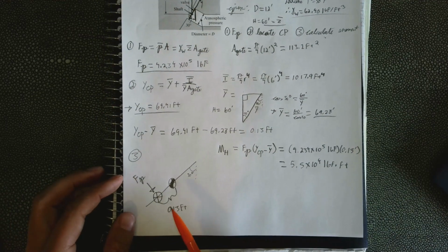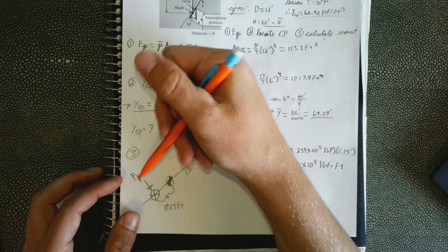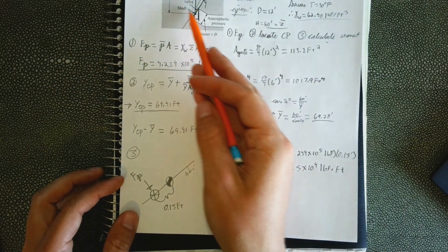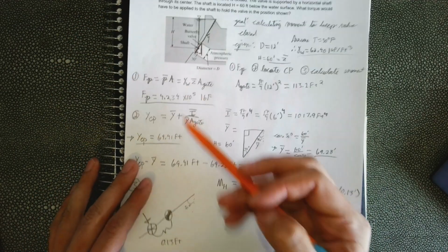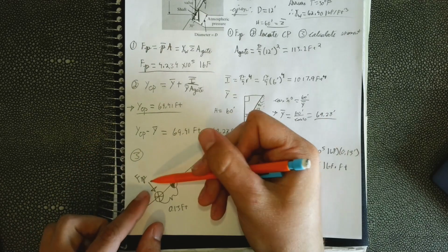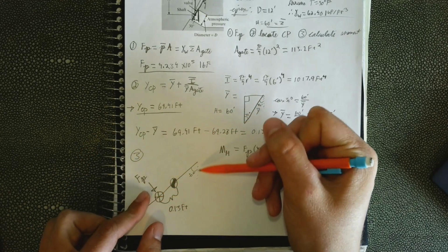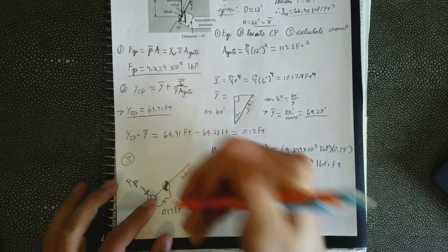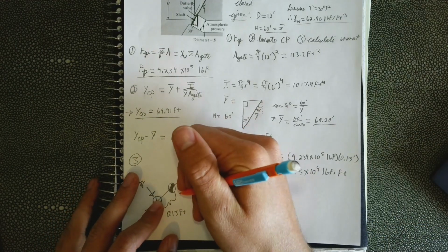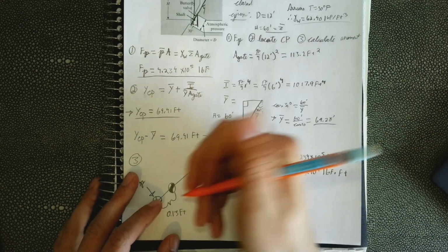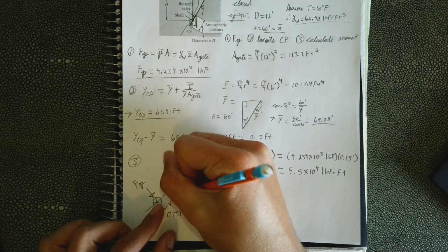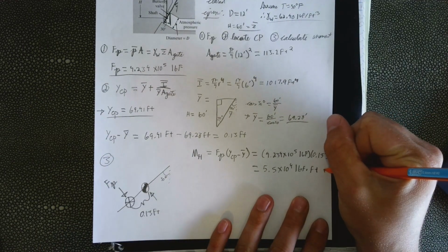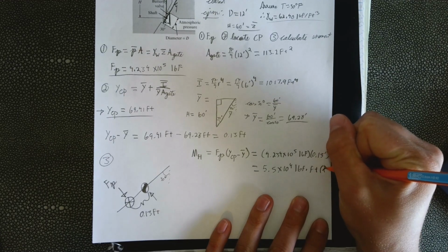And if we want to think about the direction of where the moment's going, we know that this force is coming this way, right? Because the water is on this side, so it's going to be on top. That will push this way, and that's counterclockwise. So the torque required to keep it closed from a force coming this way will be going clockwise. So the direction will be this way.